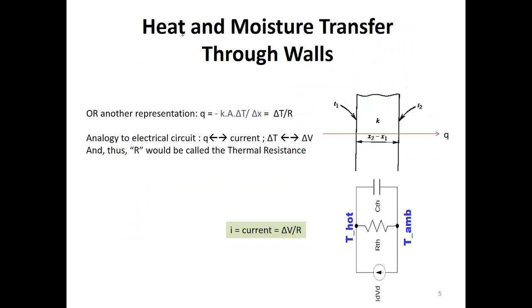So we've discussed the concept of thermal resistance. We said there's an analogy between heat transfer and an electric circuit, where Q, the heat transfer rate, is analogous to the current I. We have heat transfer because of a temperature difference, whereas here you have V in, V out, or in general a voltage difference. Because of this voltage difference, you're going to have a current going through this wire.